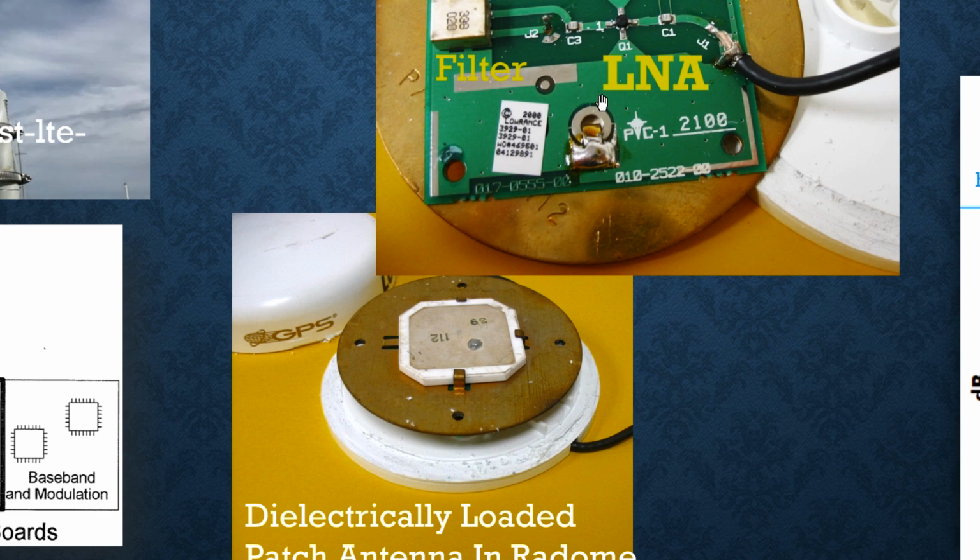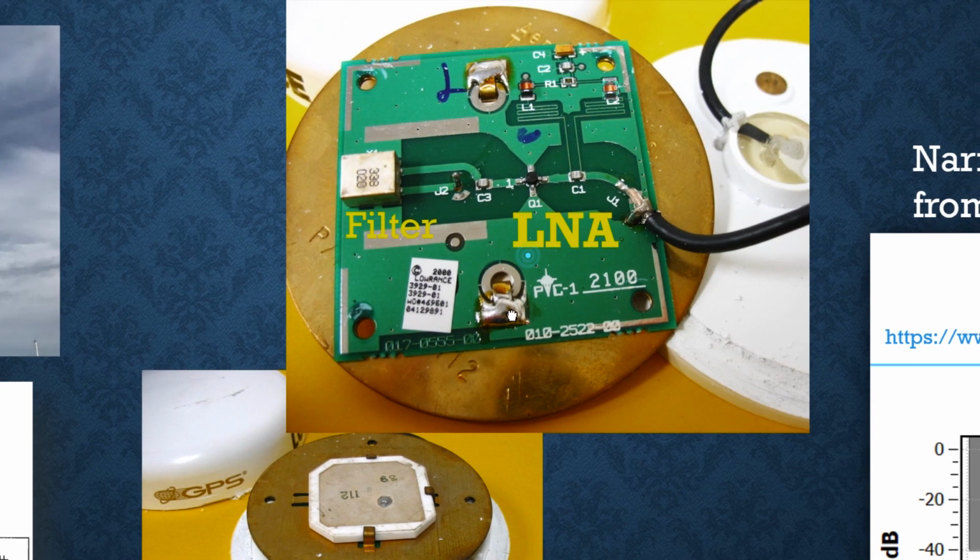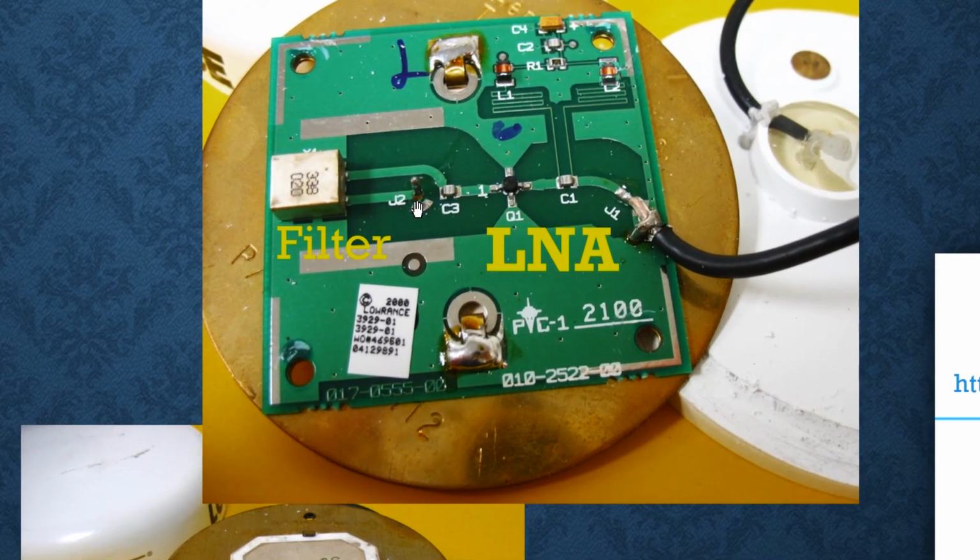So let's take a look at the electronics that's on the back side of this. So this is a metal plate, basically a ground plane, and on the back side is what we see here. The signal from the antenna comes from the other side on this pin right here. And the first thing that it goes through is a filter. This is a very narrow bandpass filter. And that's to block all of those interferers.